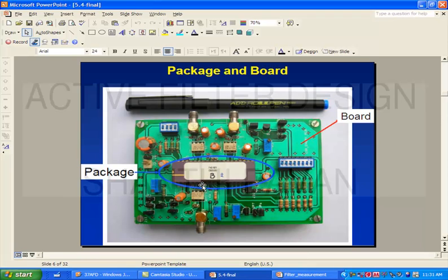So, it is not a bilateral device. Since it is unilateral, all the reverse transmission parameters in principle must be 0, be it Y12, Z12, H12, G12, S12, all 1, 2 parameters must be 0. In other words, if you wiggle the output, nothing must happen to the input, that is what it means. You understand? And the frequency response, finally you should be able to extract from which parameter? From the Y21, you are interested in the Y21, you understand?